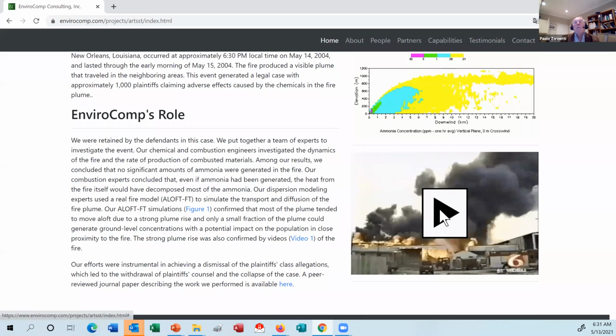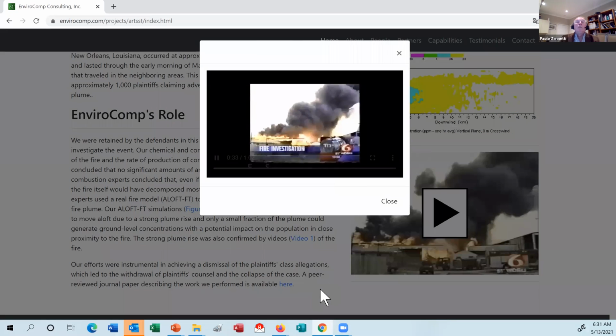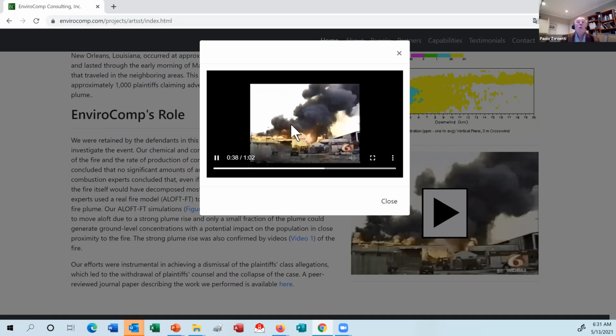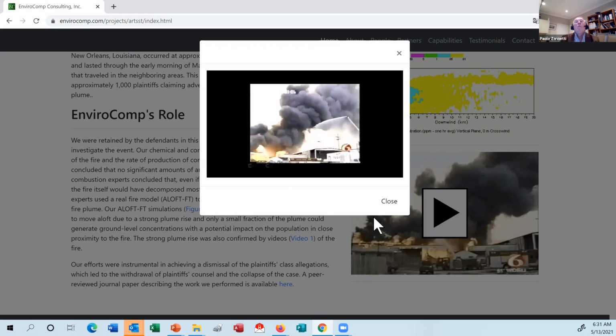I know there is a big plume rise, like this one you see, is only the beginning of the plume, but you know it's going to go high. It's going to go high. So how do you deal with that? Where is the height of the plume to run your Gaussian model? The height of the plume is at the top of the plume rise.